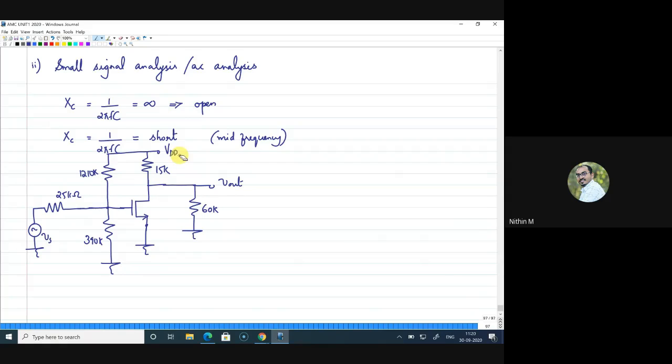And one more change is, as we discussed before, since it is AC analysis, since it is small signal analysis, no need to consider DC. That doesn't mean that DC is zero. DC is there, but since we are looking for signals which have an incremental change, signals which are changing, and DC is not a changing one, we will keep it as short. So I will make a note here. One is, all capacitors are replaced with a short.